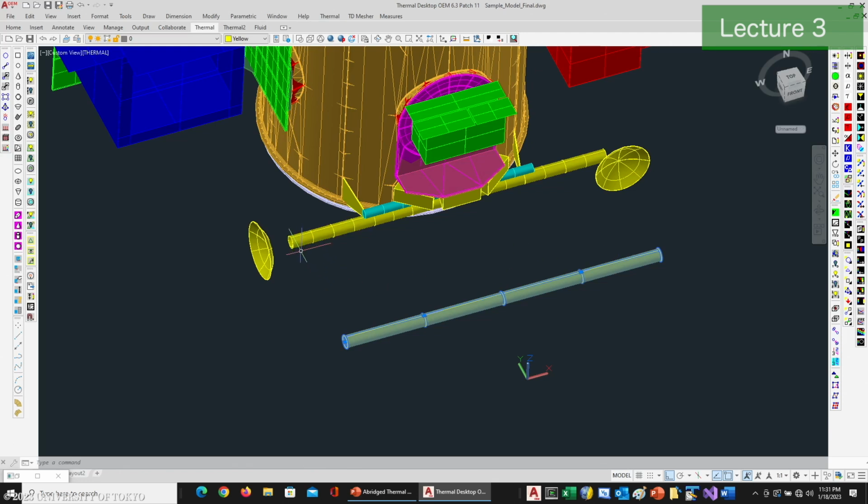You can use that for rectangles and any other surfaces where you're trying to change the lengths and things like that. So you'll notice I've got these grip points here. And there are different behaviors of these depending on what you set. So there's an RC grip boundary. And what that does is now instead of having the grip points, it lets me adjust the boundaries between the nodes or the node locations. So I could take this and move it to here instead, and now the locations of the nodes has changed.